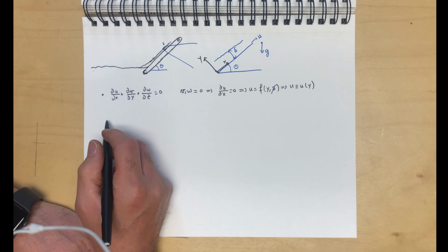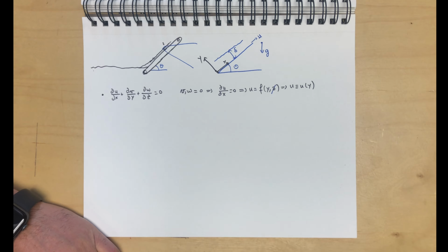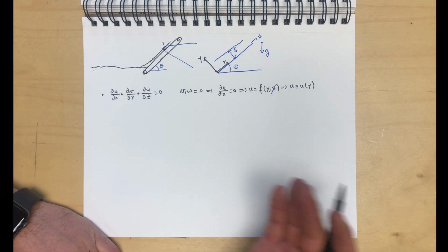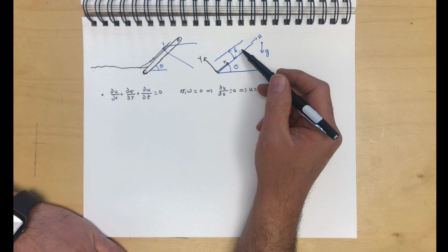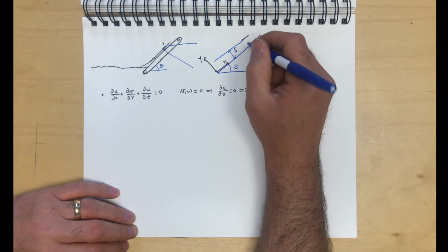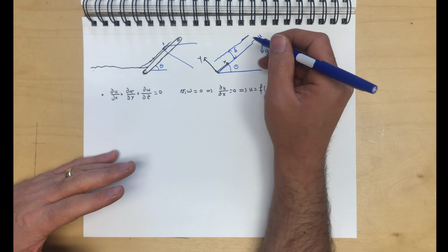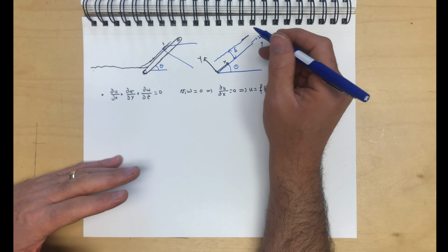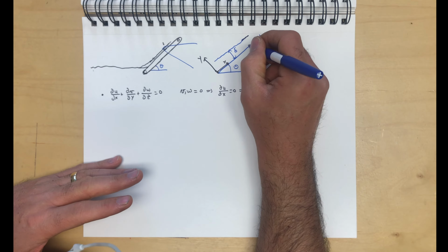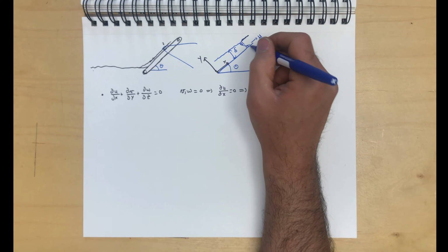Now we have the two components of momentum that matter over here. In this case, I'm not going to directly assume that dp/dx is a constant. I'm actually going to prove it this time, because we expect this to be of the Couette flow type, subject to a gravitational force. So this would actually be a combination of Couette and Poiseuille flow. Instead of having a constant pressure gradient, we have a constant gravitational pull. And so what we expect to have here is a velocity profile like this. So this flow is coming up here, and the flow is going down in the other direction.